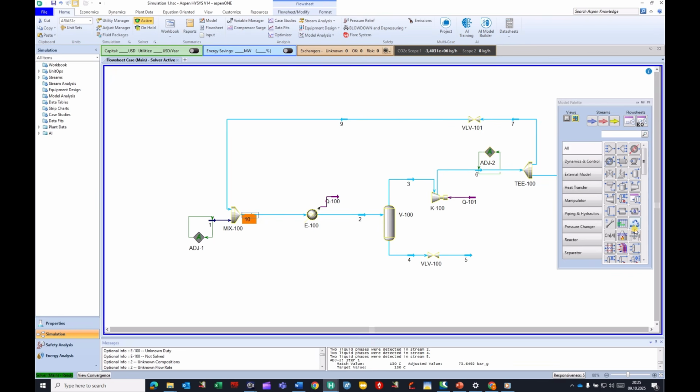Recycle operation, you can find it here. It can be in many locations, but it's very critical for the recycle operation. First of all, you should limit the number of recycle operations to those you definitely need. No additional recycle operations in the simulation leads to a good simulation. In addition, the recycle operation should be located in a location that defines the maximum number of variables, and also prevents unnecessary usage of more recycle operations.